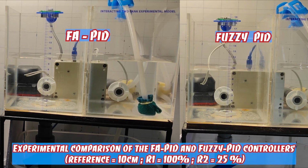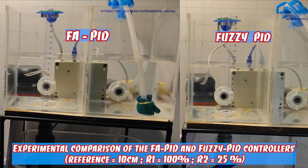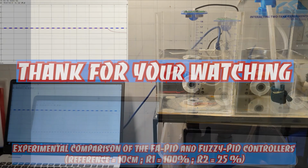Another remarkable feature of the FA PID controller, as you can see, is that once the system reaches steady state, the response shows almost no oscillation around the reference level. In contrast, with the fuzzy PID controller, you can observe small fluctuations of about 2 mm around the reference value. This can be clearly seen with the naked eye in the experimental video on the left side of the screen.